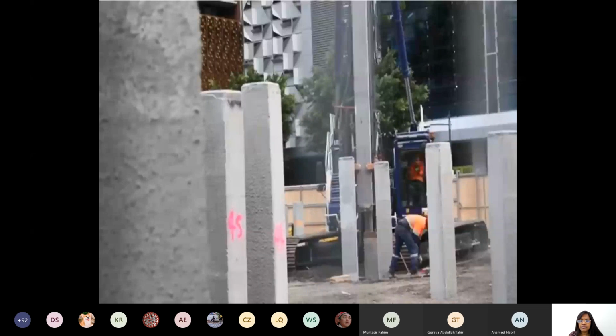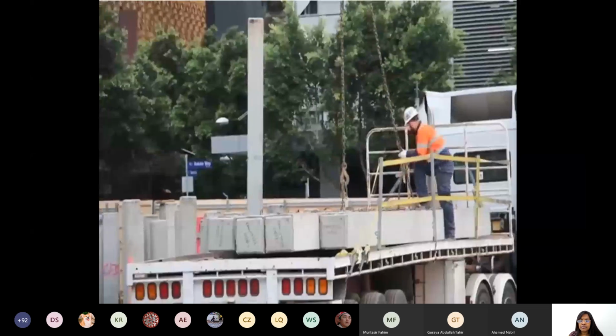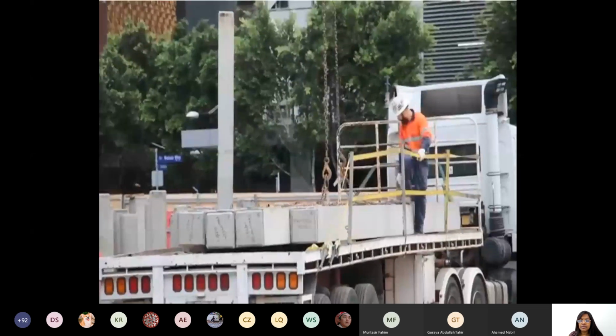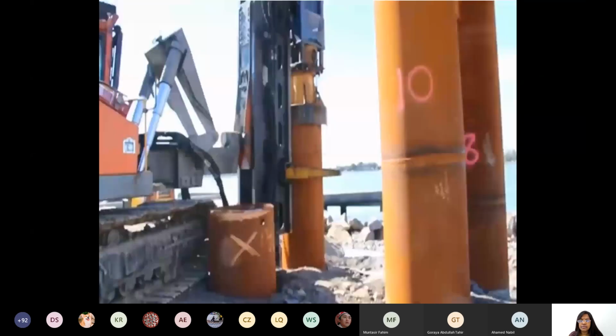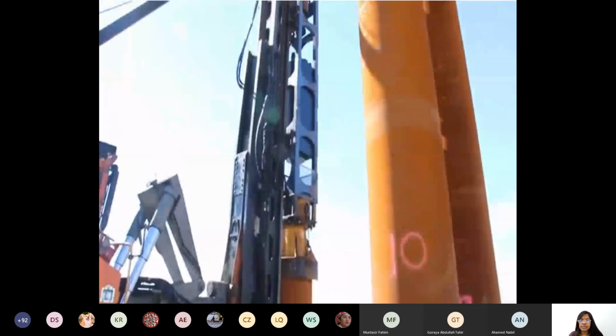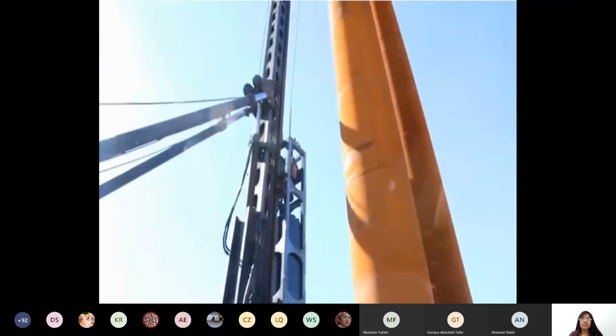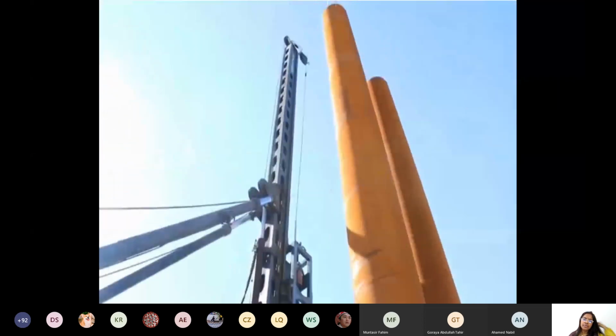Pile driving technology is a process where already built piles are driven into the ground with the help of a piling rig and an impact hammer. Piles can be concrete precast piles, steel piles, or wooden piles, depending on the required application, grounds, feasibility, and so on.